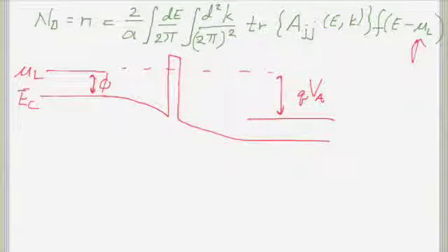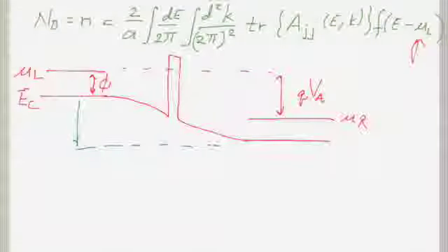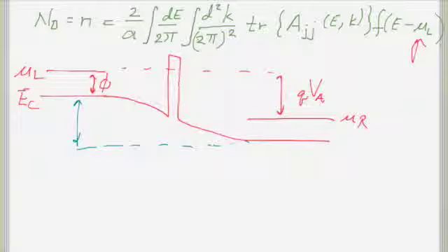So the Fermi levels are split by the applied bias, which means that the difference in the potential in this case from here to here is also whatever the potential was in the source over here for this boundary condition, your potential on the left, plus, and I'm going back and forth between electrostatic potential and energy potential, plus your applied voltage.